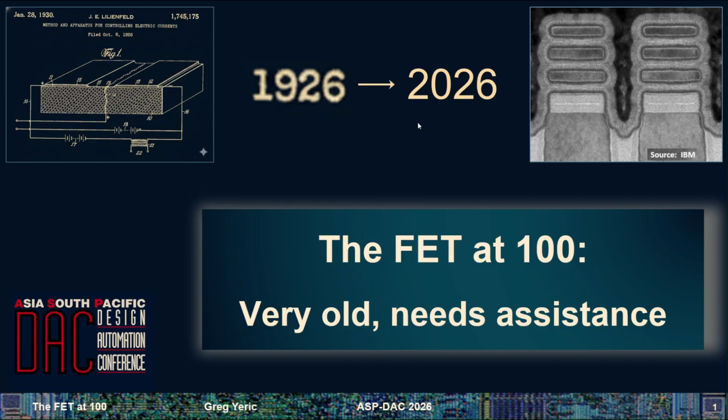Let's see if we can head off some questions here right away. At the upper right, this is a modern gate-all-around FET. So this is a cross-section of a wafer. The horizontal rectangles are your channels. So the current is going in and out of your screen, and wrapping around those is the gate material. We talk about those, of course, in the class later.